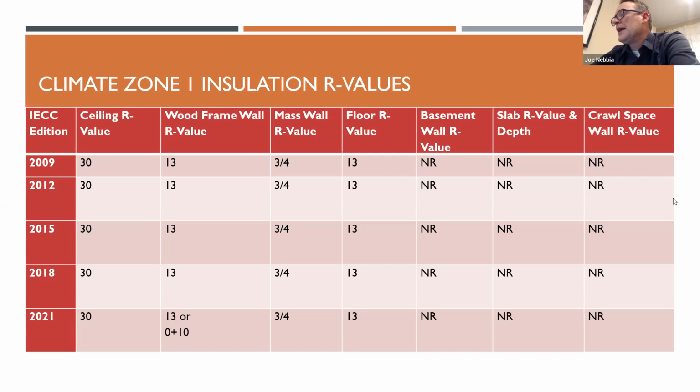Right. I could not find any current exception in the code for impact resistant glazing. I do believe there may be some local amendments that deal with that question and acknowledge that some impact resistant glazing may be less focused on U value and more focused on hurricane resistance. Obviously, we're going to pick a life safety issue over the U value of the window. But I do know that there are many manufacturers who have hurricane windows that are also meeting these U values.